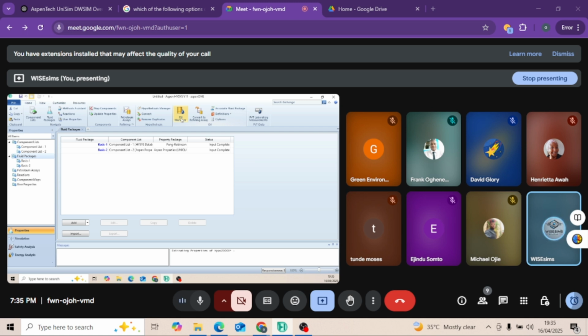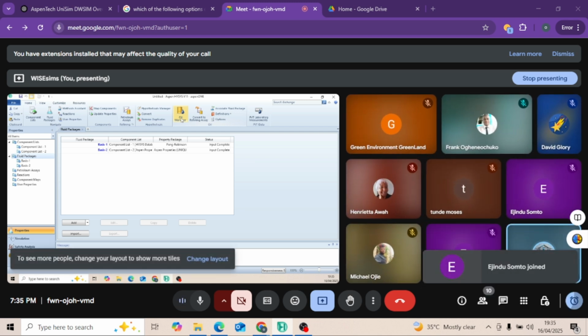The assay contains things like viscosity, the boiling point of your crude oil, the components in it. You understand? The components in it, that's maybe your methane, ethane, propane, thereabouts, down to decane and all that. So those things are found in your assay, as well as, like I said, your viscosity, your true boiling point. All right.